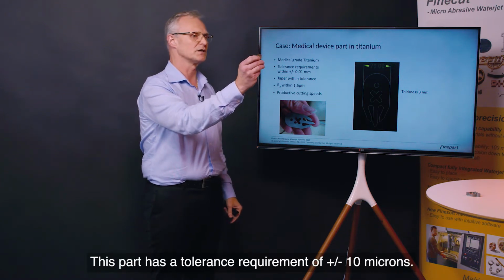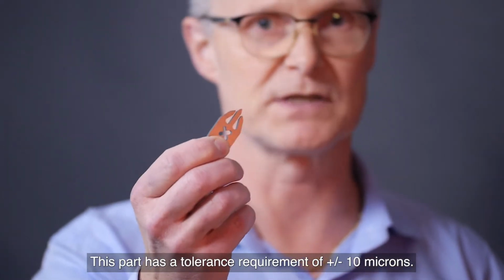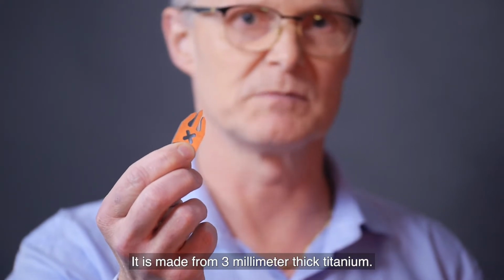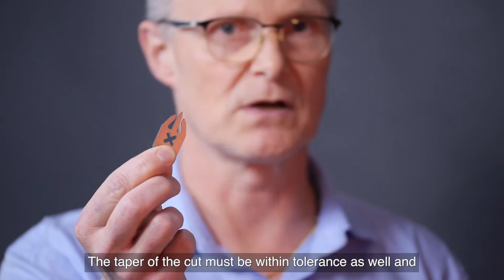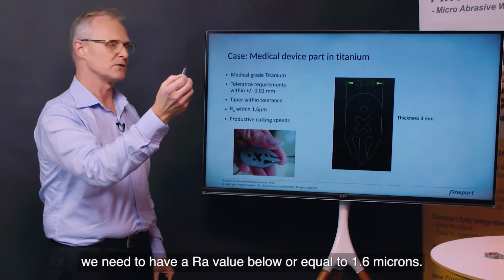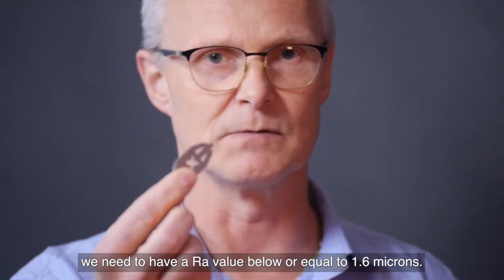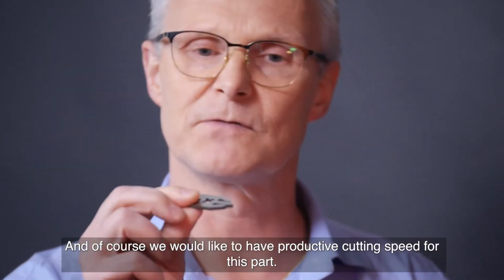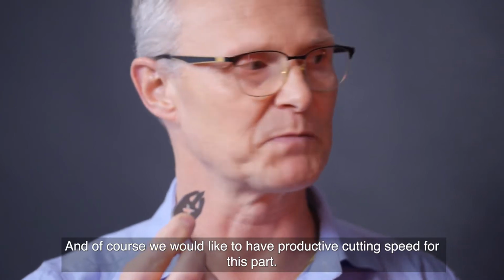This part has a tolerance requirement of plus minus 10 microns. It's made from 3 mm thick titanium. The taper of the cut must be within tolerance as well, and we need to have an RA value below or equal to 1.6 micron. And of course we would like to have a productive cutting speed for this part.